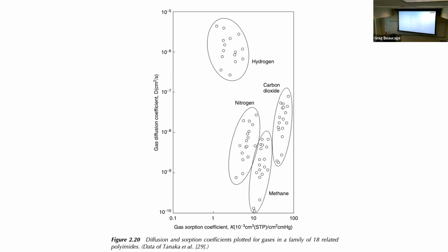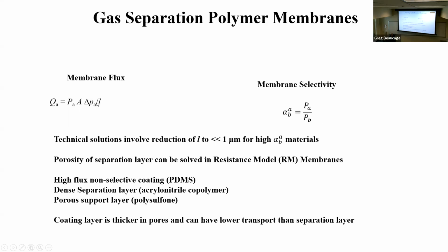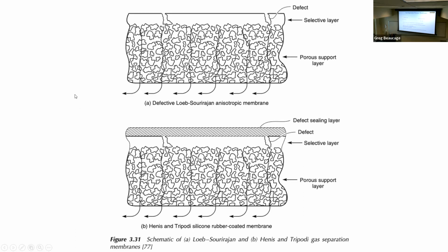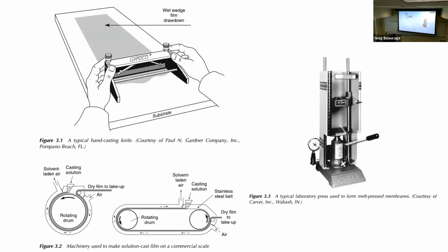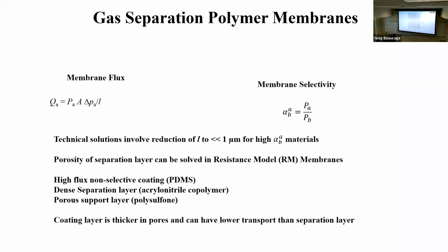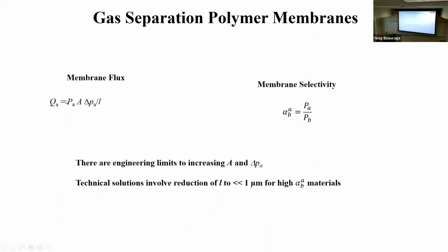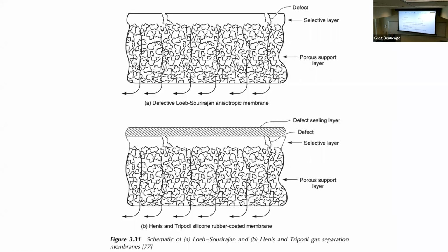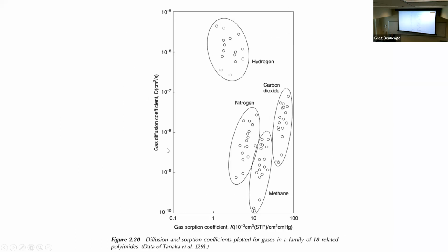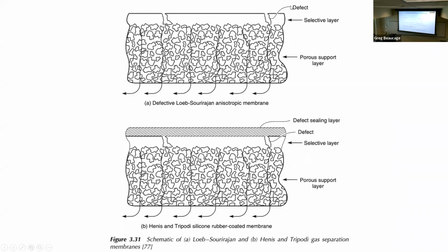All right, this is also gas separation membranes, just showing the transport issues. The two things in this equation are the permeability. Permeability is made up of solubility and diffusion coefficient. Anyway, P is solubility times diffusion coefficient. It's definitely written here someplace, but this is a map of diffusion coefficient and solubility. So basically, you want to be up here to get a good permeability for the membranes.